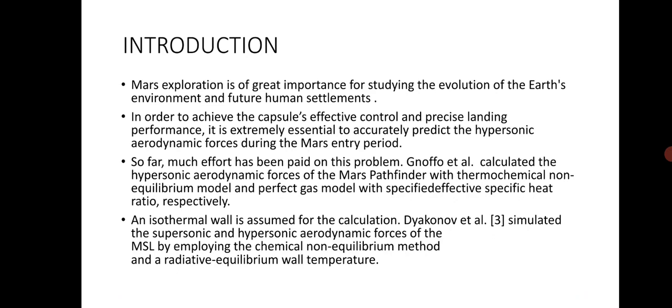Calculated the hypersonic aerodynamic forces of the Mars Pathfinder with thermochemical non-equilibrium models and a perfect gas model with specified effective specific heat ratio respectively. An isothermal wall is assumed for the calculation.